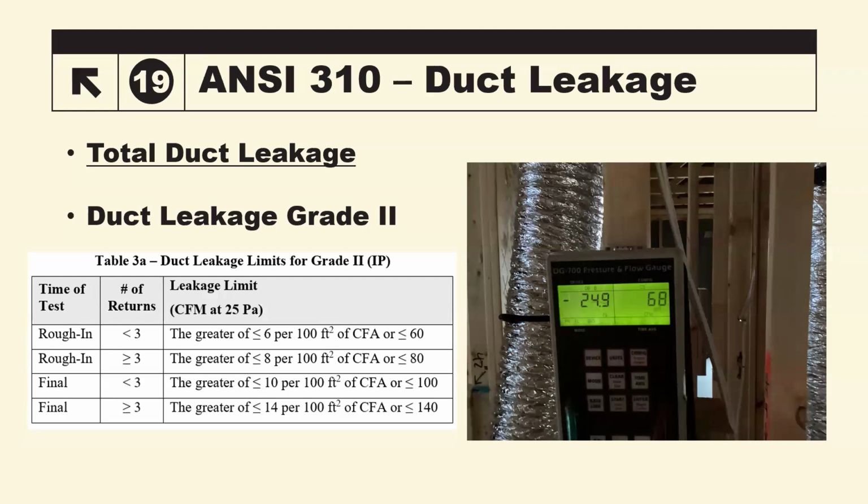And keep in mind, if you're looking at code, and this was always tough for me when I did training for inspectors, we're doing two-system duct testing and one's failing miserably, but one's passing considerably at a very low leakage rate. For code, it's leakage per the whole house, not per system. So if you're looking at 4 CFM per 100 square feet, as long as both of those numbers add up to 4 CFM or less as a whole, the house passes. Is it acceptable to leave it that way? No. If it's really leaking on one of the systems, it should be corrected, because that leads to imbalances and all these different things that we go down rabbit holes with all the time.